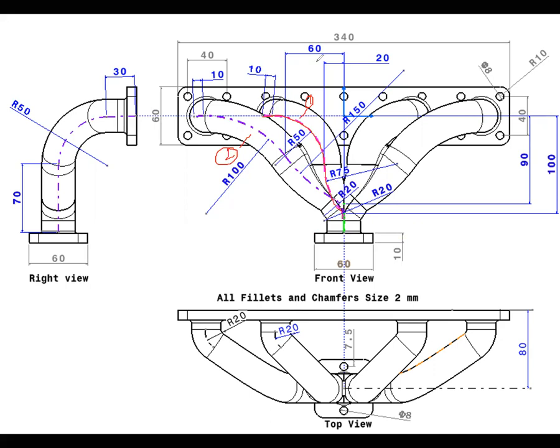So how to create that one? We select the YZ plane and line and curve. You can choose an arc with radius 50, and again another curve. The center point of this arc is somewhere, and both are tangent, up to the vertical axis. From here to here is 90. Actually, we can get this arc using 3D corner, up to here only 90 millimeter.